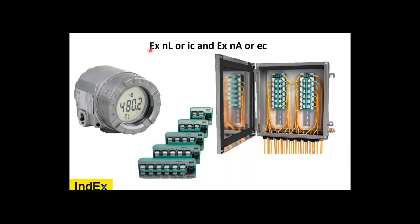NL can't be out in open air, so you had to put it inside of a junction box. What was the zone 2 junction box available? NA. So the NL went inside the NA, which fed an NL circuit out to an NL instrument. But as the standards updated at different times, these internals changed to IC. IC can be inside of a control room as long as it's IP20.